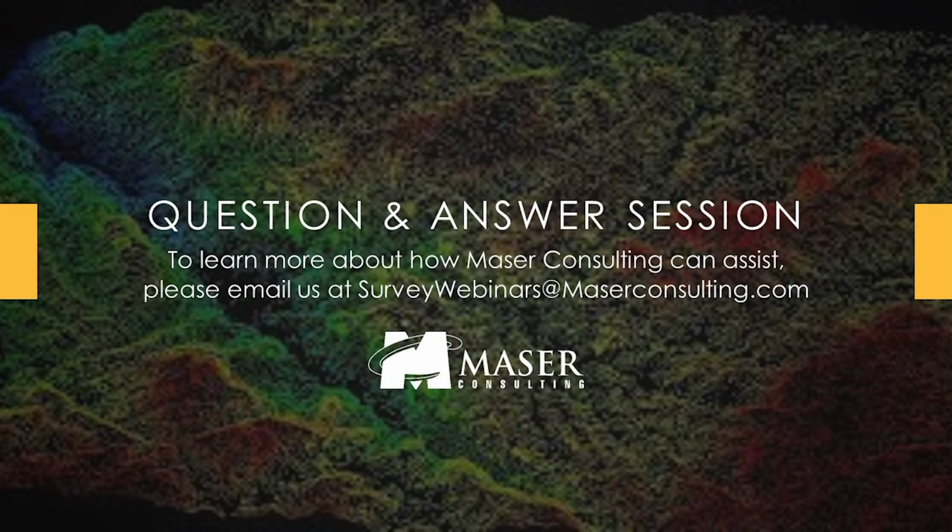LiDAR doesn't penetrate water. So stream crossings and stuff, we still have to pick up conventionally. Really, the way I look at it and the way I approach projects is, anytime I'm required to provide a 3D deliverable where the Z component is crucial, I am using LiDAR over photogrammetry every time.